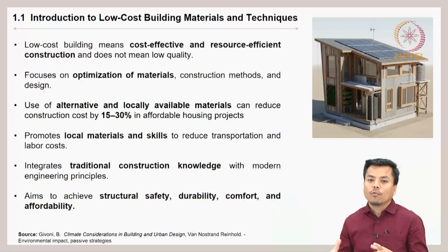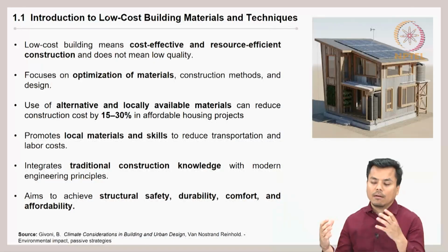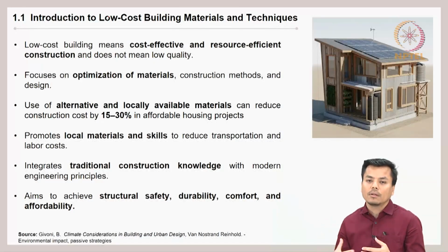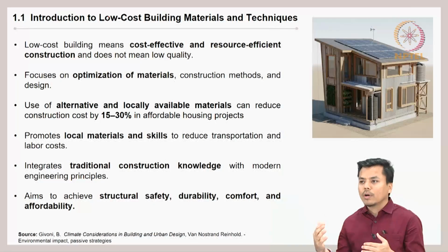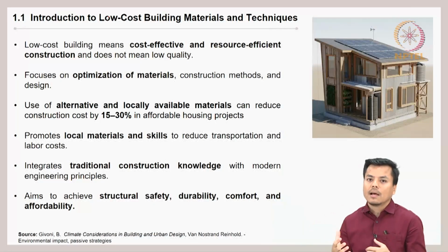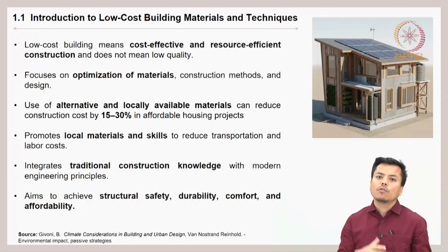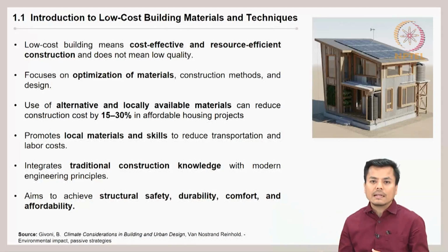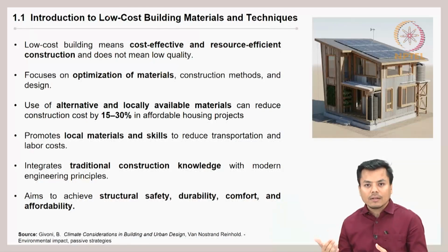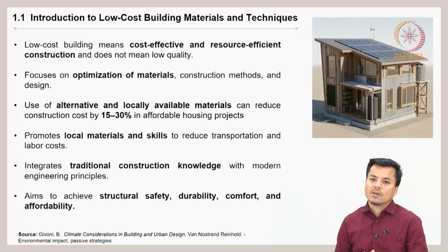If you follow this particular technique, then you minimize the cost that goes on the formwork, or you can also estimate based on whatever construction has happened in the lower floors. You can estimate how much more material will be required, and if any mistake has happened, you can correctly rectify it and reduce the wastage of materials while you construct the upper floor.